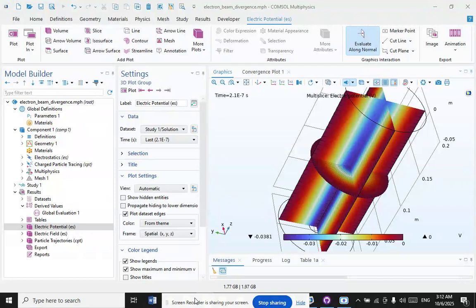The next concept is a fundamental investigation into the role of beam focal point and beam divergence on capillary stability and evolution in electron beam welding applications. In this simulation, a novel mathematical framework that fully describes fusion and vaporization state transitions in multi-component substrates has been applied to assist in understanding the fundamental mechanism of thermocapillary or keyhole formation and stability during the electron beam welding process.